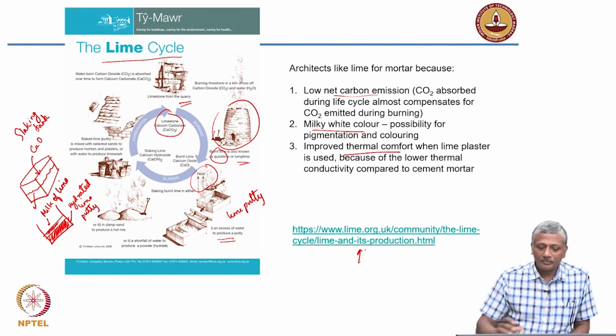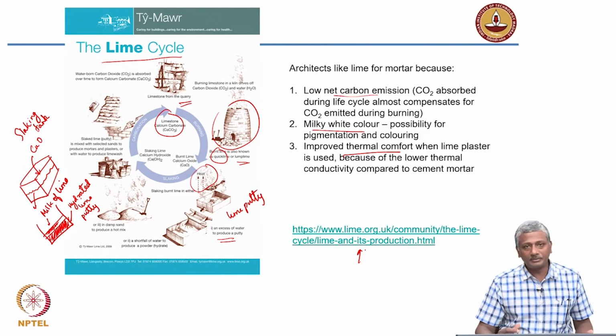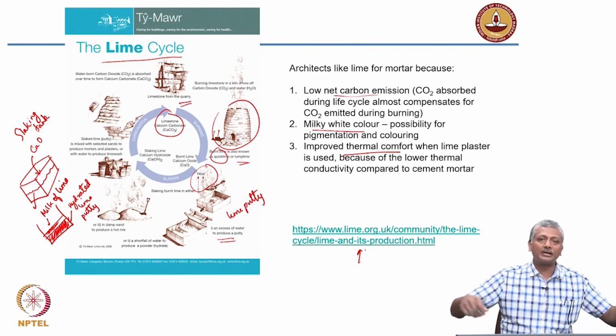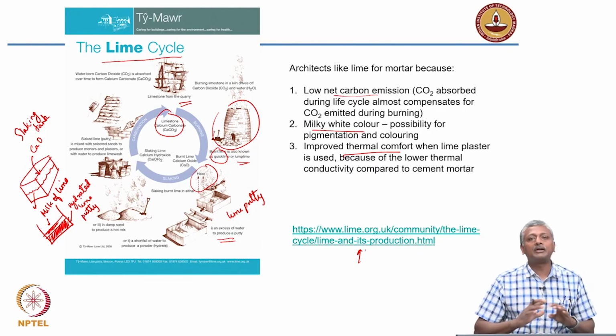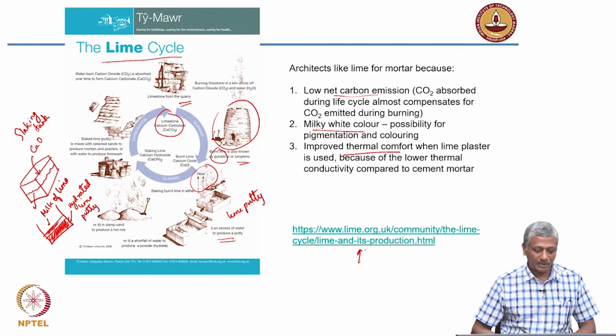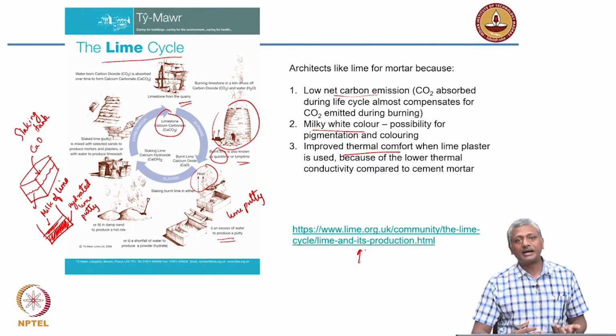Now, not all slaking practices are perfectly optimal. In some cases, people just dump the lime on the floor, mix the water into it and continuously mix it for a long time until all the heat dissipates. So, it depends on how the lime slaking practice is done at the site. Once you mix it up with sand and make the mortar, it has to be in the hydrated lime form.